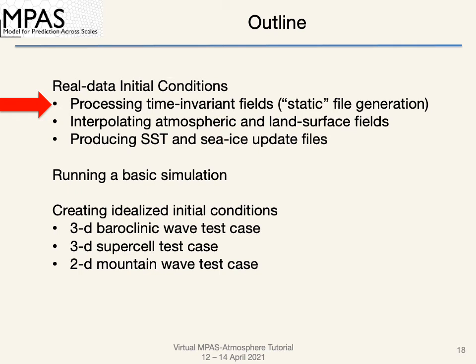So we've just seen how we can run the init_atmosphere model program to create this static netCDF file that has all of these time-invariant terrestrial fields. And that, as we said, takes about 45 minutes, but because these fields don't change in time, you only need to do that a single time for a given mesh.